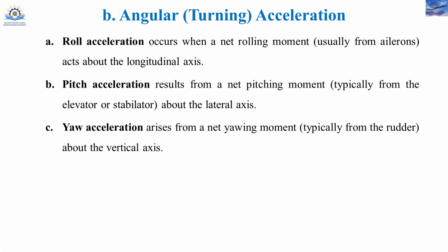Another is pitch acceleration, which results from a net pitching moment about the lateral axis. That can be achieved with the help of the stabilizer. The stabilizer is a combination of stabilizer and elevator. So the stabilizer and the elevator together perform the action. Those are the control surfaces.